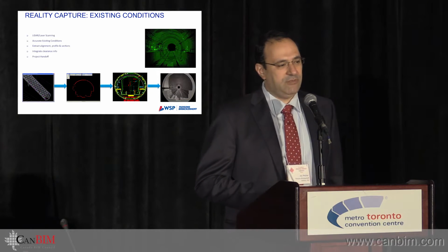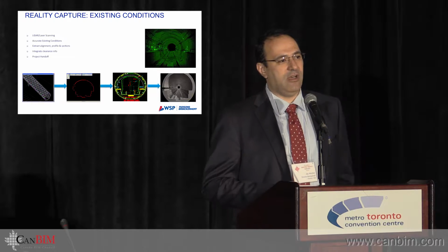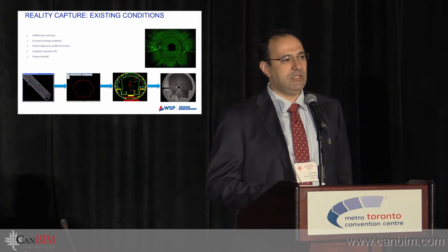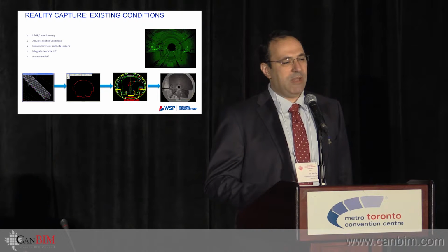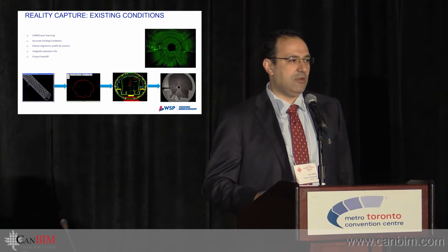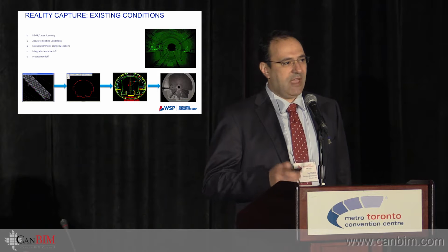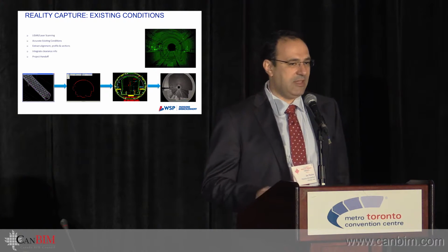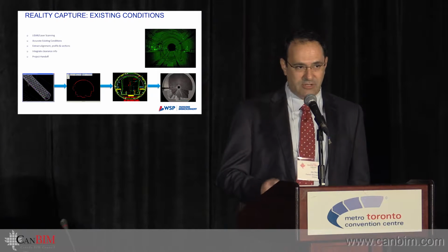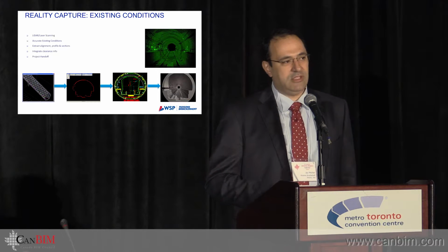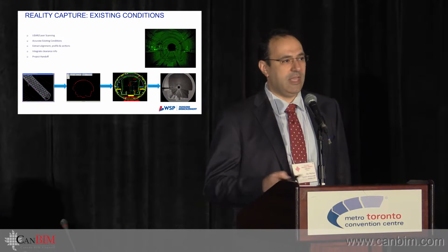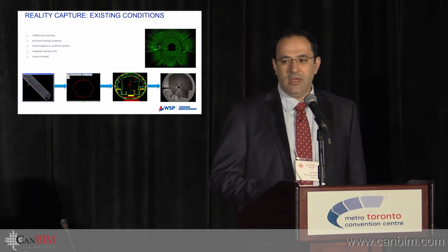The other use of laser scanning has been project handoff. On a lot of projects that involve multiple contract packages, when you hand off one package from one contractor to the other, there's certain tolerances that you have to be within in terms of construction, and the only way to identify these tolerances and to make sure that the contractor built the job according to the design is to laser scan it, overlay it with a design model, and then approve the work.